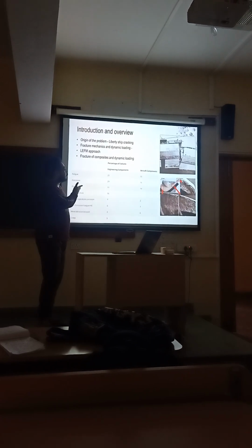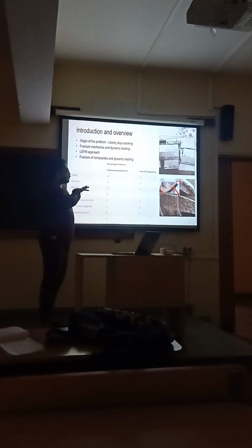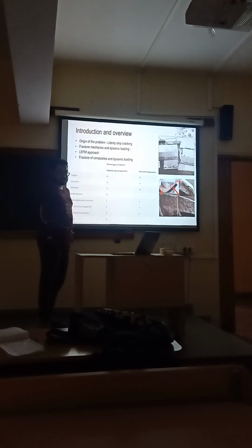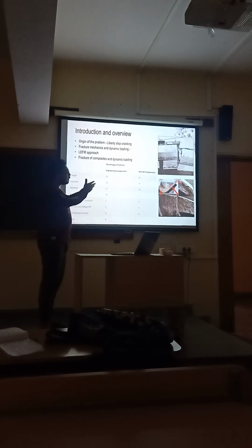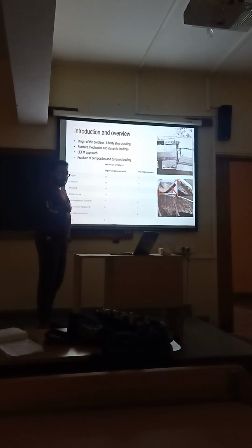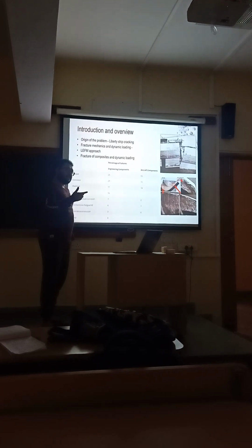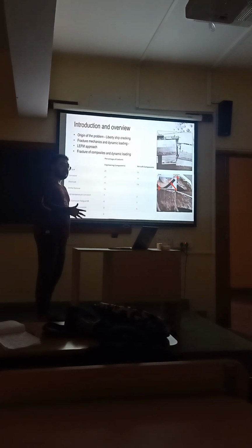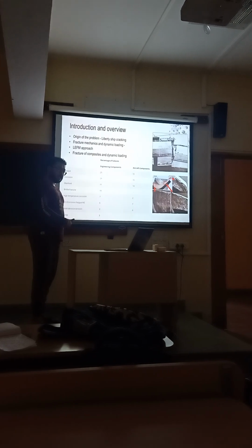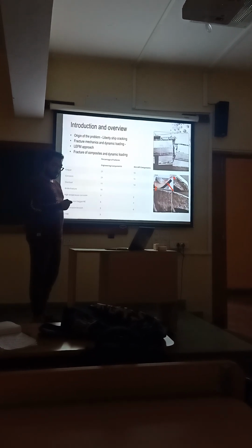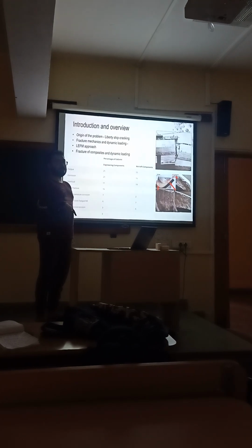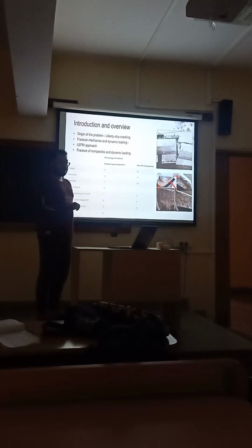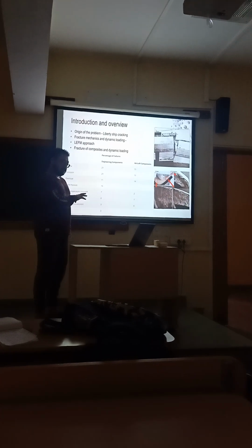Now, how did this happen? Initially, for ships or aircraft, riveted junctions are generally preferred, but due to the shortage of labor, they welded the entire hull. Now, the North Atlantic in December has very harsh conditions, and along with the dynamic loading, the defect in the hull propagated and accelerated rapidly, resulting in this phenomenon. This came into the picture in this year.